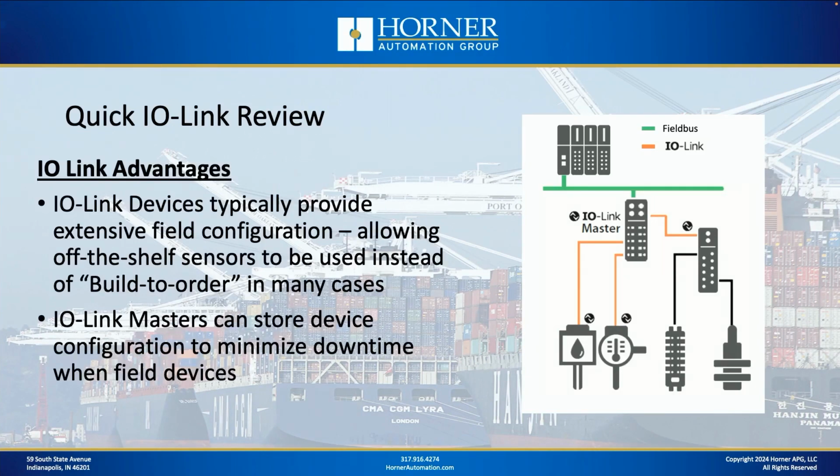Now, there are plenty of advantages to IO-Link. One advantage is that IO-Link devices are very often highly configurable in the field, preventing you from having to order special factory options. A lot of the time, you can just go ahead and make the modifications in the field yourself by adjusting the parameters on the IO-Link device with IO-Link software. And we'll show you how to do that a little bit later today as well.